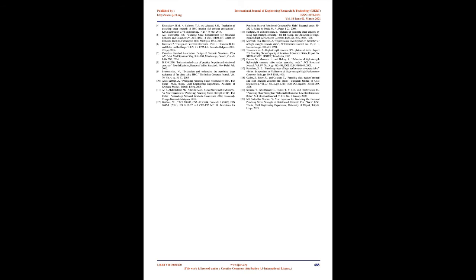Conclusions. This parametric study showed that the significant parameters that primarily affect the punching shear behavior of slab-column connections of flat plates are concrete compressive strength, slab effective depth, flexural reinforcement ratio and critical perimeter. Despite being a simple equation, the new proposed equation includes the main four significant parameters, f'c, ρ, d, and b0, and can predict the punching shear capacity with a conservative and reasonable accuracy compared with other available design codes.